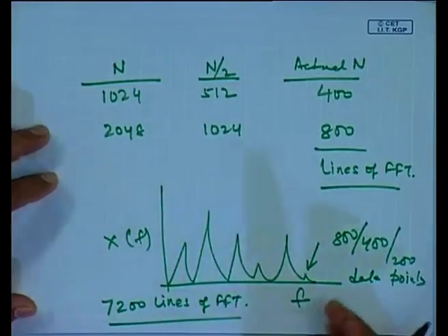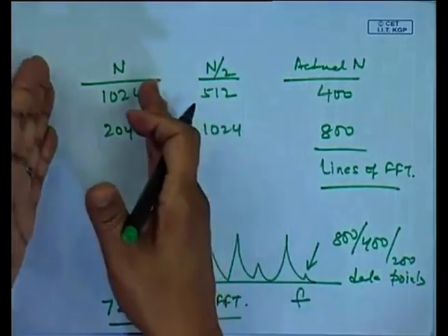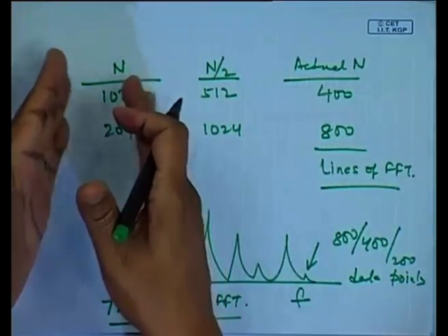This means 2048 data points in a block are taken, the FFT analysis is done, and the results displayed. Nowadays, with FFT analyzers, I can either do it through the software given by that equation or even implement it in hardware where all these computations are done. FFT computations also take time.